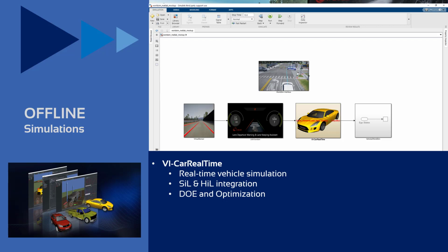Car RealTime fully supports software-in-the-loop modeling through either a Simulink or a direct MATLAB accessible solution. Car RealTime allows you to deactivate subsystems and replace or augment them with Simulink models. The solution can be run native in MATLAB, useful for control design engineers. It also supports a compiled auxiliary subsystem approach for bringing in models for running in a Car RealTime native environment. Both solutions support an investment mode for efficient design of experiment studies and optimization.